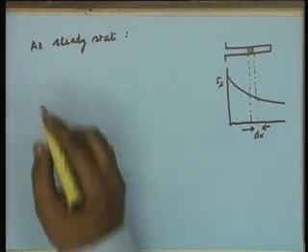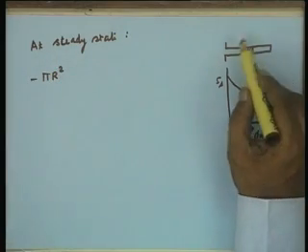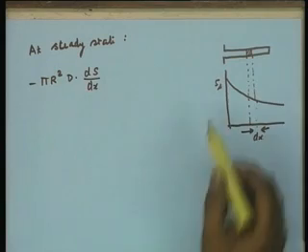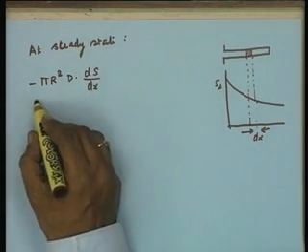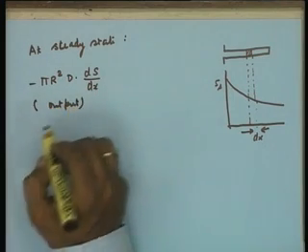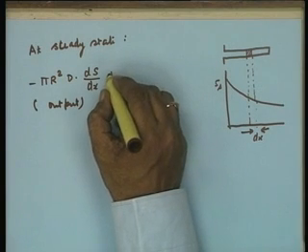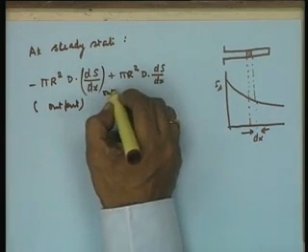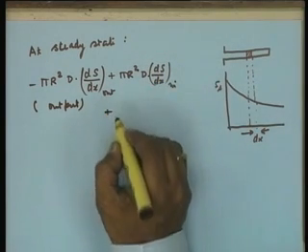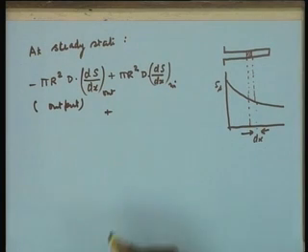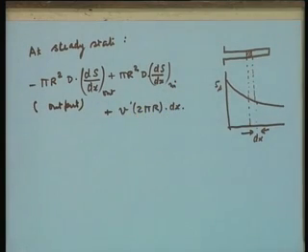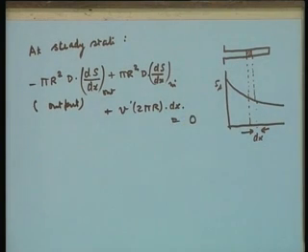You see, the output of the substrate will be minus pi r square D into dS over dx, where r is the radius of the pore. Of course dS over dx is negative, and therefore this is essentially your output of the substrate from the pore, minus input, that is plus pi r square D into dS over dx. Sorry, this can be out. Input plus the conversion as a result of the biochemical reaction, that is V dash into 2 pi r into dx. Now this should be equal to 0, as at steady state we make a mass balance for substrate across the differential element.